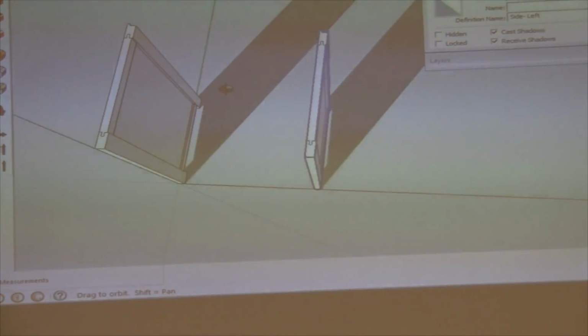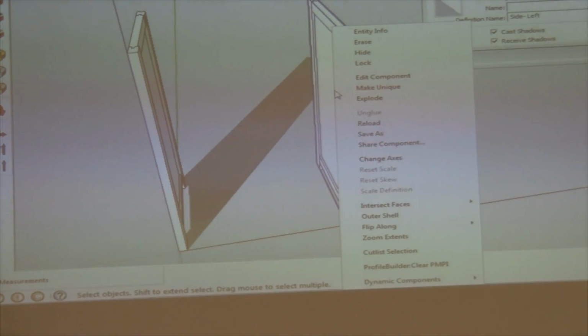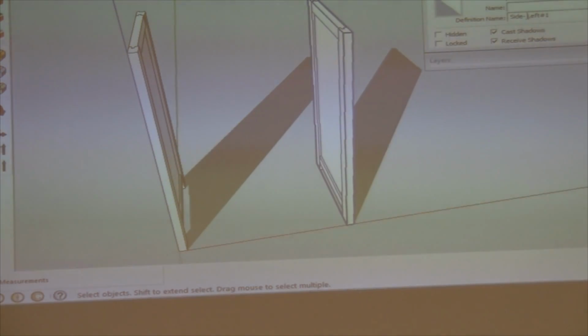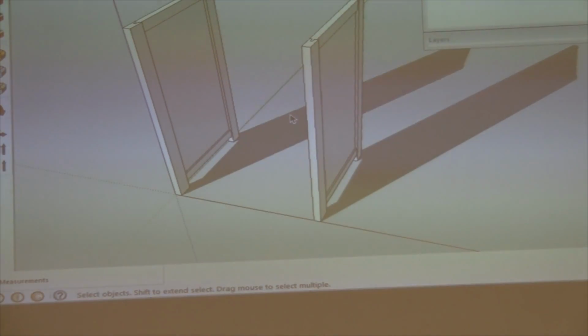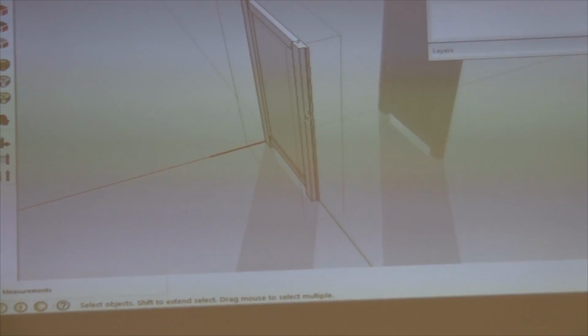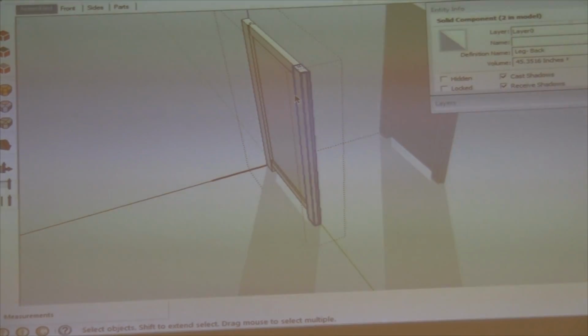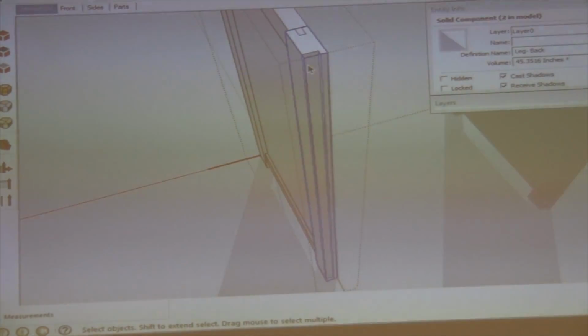And we can't simply flip it because we have 1.5 inches reveal off of the bottom and we're flush on the top here. So we're going to simply take this component, make it unique, call it side right, and then move some of the components around. Okay, so the first thing we're going to do is come over here and take this right leg, or this back leg on the right side, and flip it. You have to double click to edit any component.